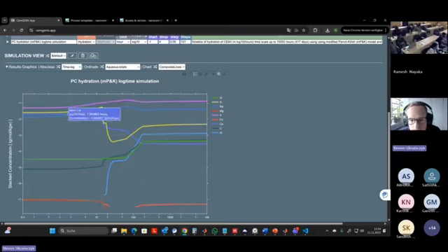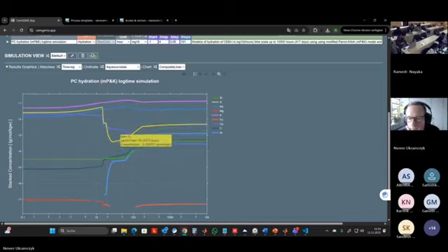No, sulfate. A lot of sulfates at the beginning, and then there is precipitating ettringite. Then it's less sulfates. Here is probably monosulfate. Here is ettringite, I guess. Then we have the calcium concentration, and you can see how with time you can predict the pore solution concentration of your cementitious system.